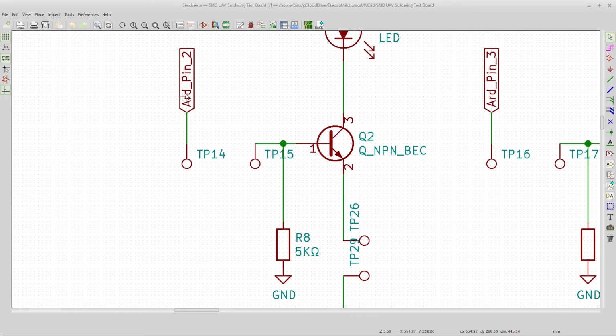And you see, here's where it comes in. There's going to be a wire that jumps from here to here. This is because it's a solder practice board. Normally it would just be straight connected. And so when that signal happens, it says turn on, then it's going to put a small voltage, 5 volts, on this pin right here of this NPN transistor, which will be the equivalent of pushing the button. And so then it will turn it on.